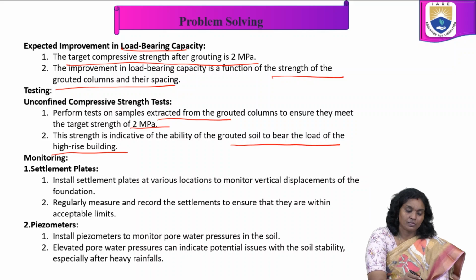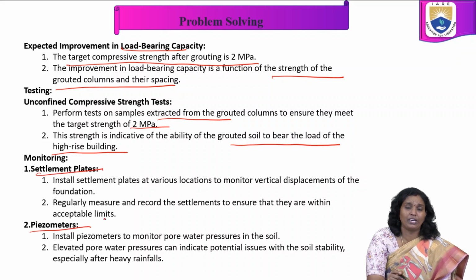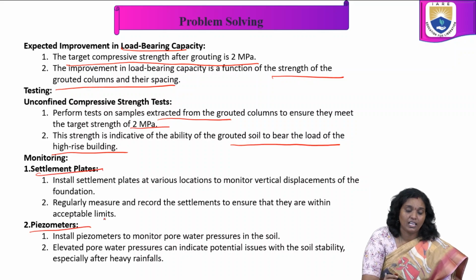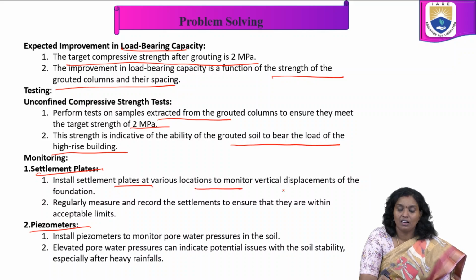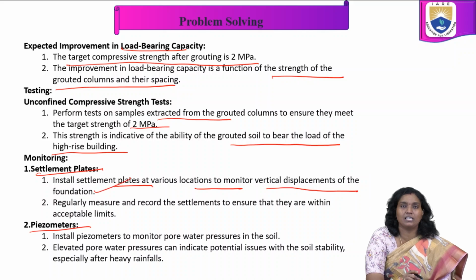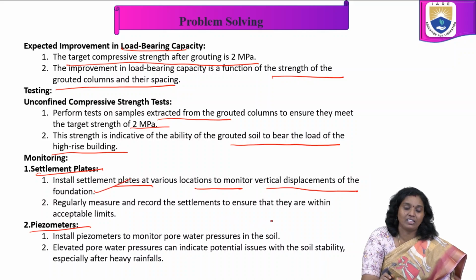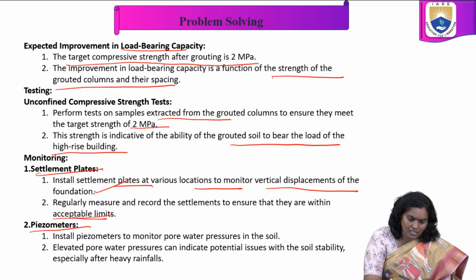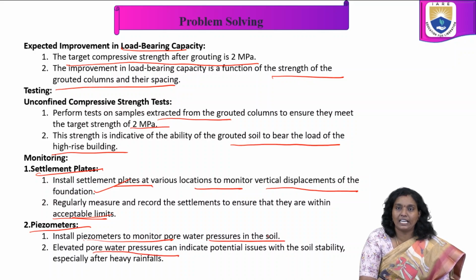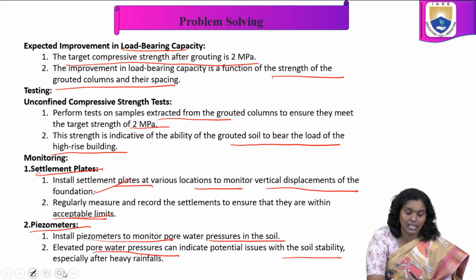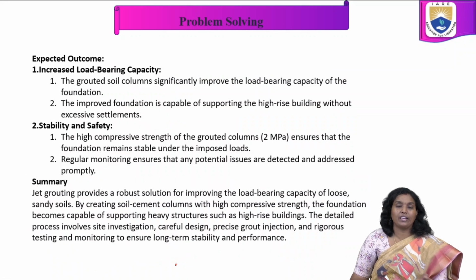In this, the settlement plates and piezometers are going to be monitoring. So install settlement plates at various locations to monitor vertical displacements of the foundation. Regularly measure and record the settlements to ensure that they are within the acceptable limits. In piezometer, install piezometers to monitor pore water pressure in the soil. Elevated pore water pressures can indicate potential issues with soil stability, especially after heavy rainfalls.